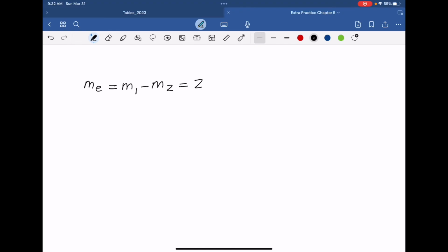So initially it was 259.4, and 129.7 kilogram exited, and then the remaining should be half of it. Okay. So now all your masses are known: M1, M2, exiting mass. Very good. So the next thing is we need to look at state properties at the second state, because we need information about the internal energy for the energy balance. Otherwise we cannot solve the energy balance. We need U2. So let's take a look at state 2.